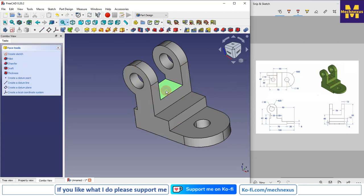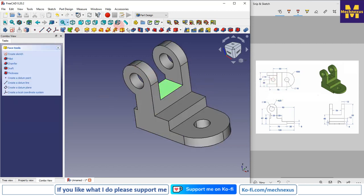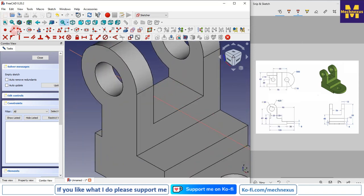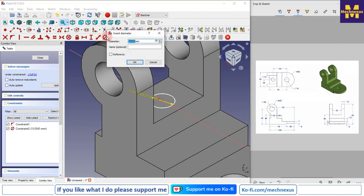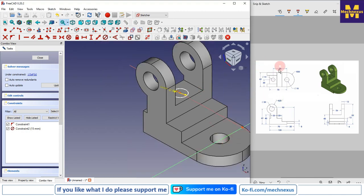Now there is a hole on this face, so I will select this face and simply select a sketch and I will draw a circle which is of diameter 15. And the position is 55.